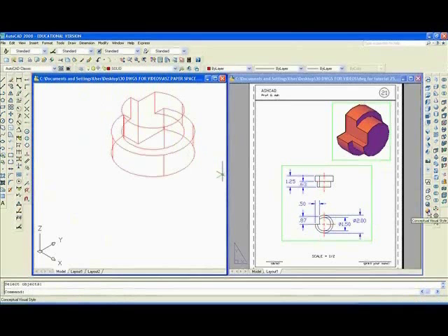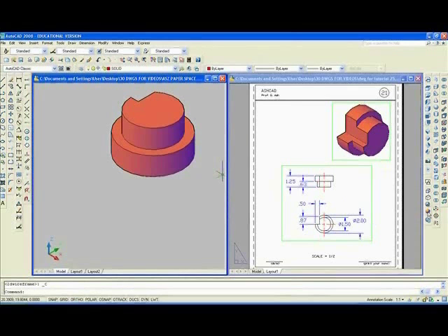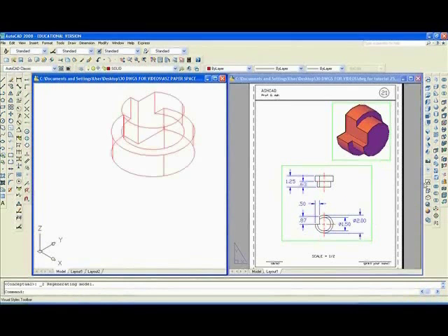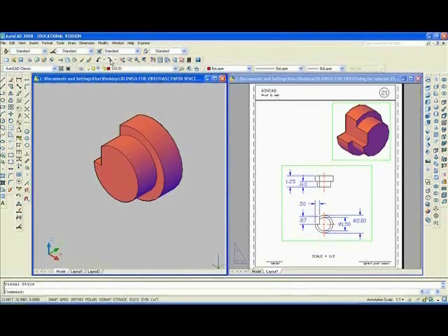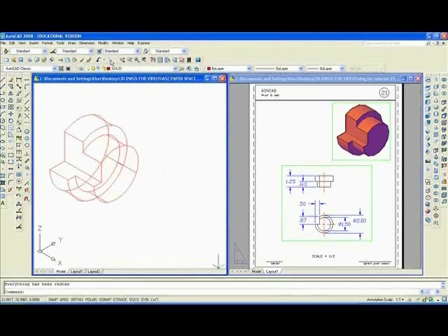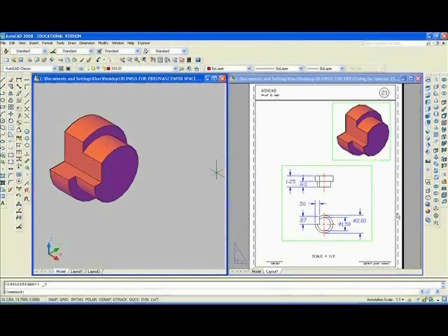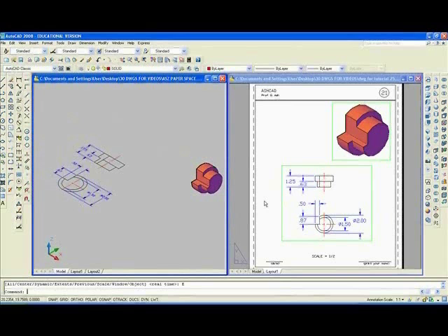Now what I really want to do is see what it looks like. Okay, so I'll go back to the wireframe model. So now we'll have to use the 3D rotate command, and so let's see what it looks like. Alright, there it is. Just rotate it 90 degrees twice, and it looks correct. It is correct. We'll Z enter, E enter.